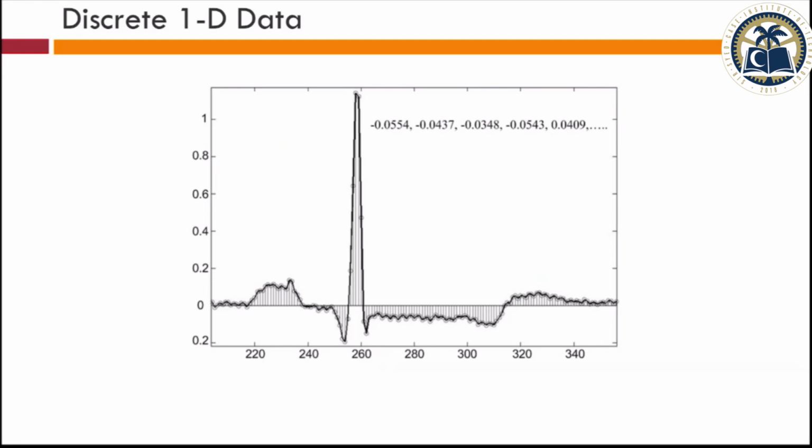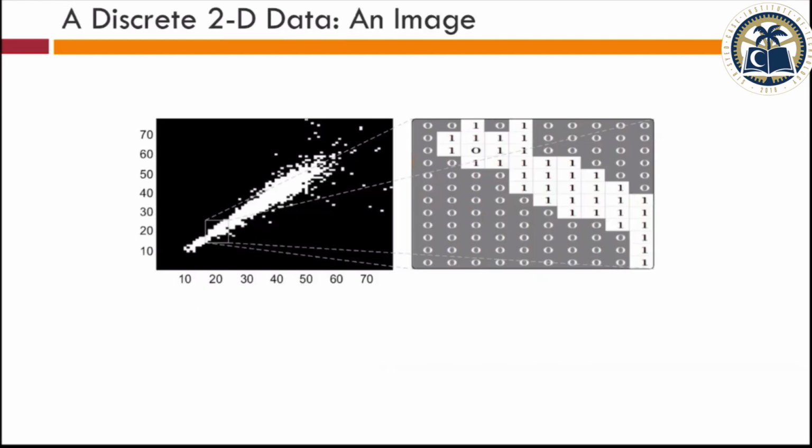Okay, so a register is also a delay, a one cycle delay. Once there is a register, it means you are holding the next computation back by one cycle. So there is a previous value, then there is a new value. So a register means a delay as well. But this is how a synchronous digital logic would look like.